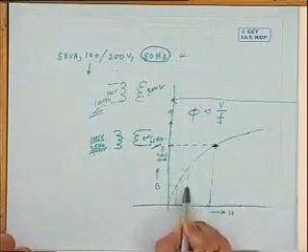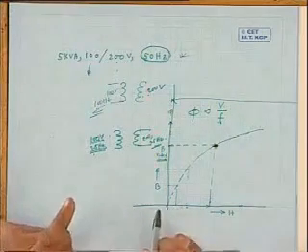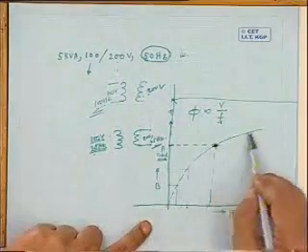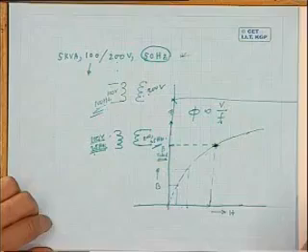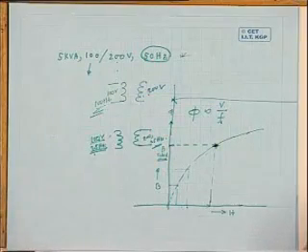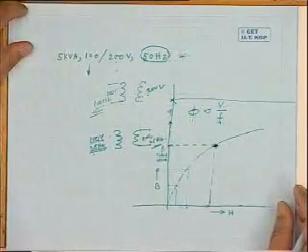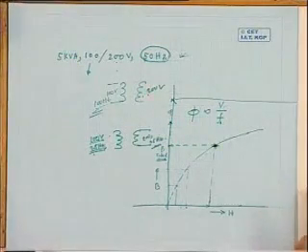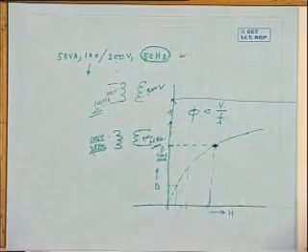Suppose a transformer is designed at this level, then of course if you reduce the frequency, the magnetizing current will become twice, like that I can say. But that twice thing does not hold good because of the bend in the BH curve of the material. Okay, so at lower frequency of operation with the same voltage, you cannot do it.